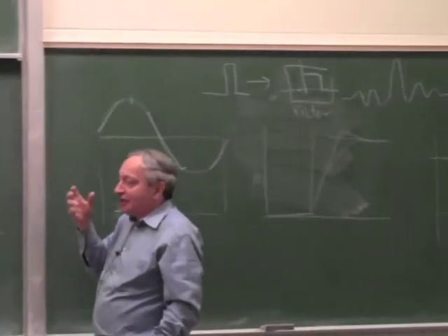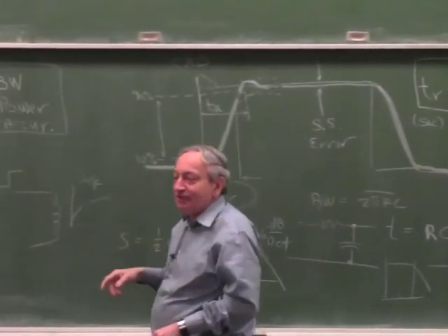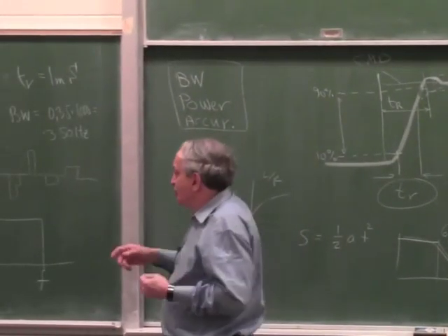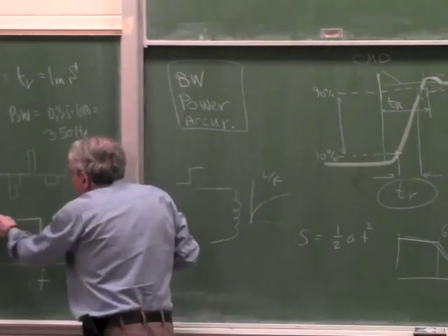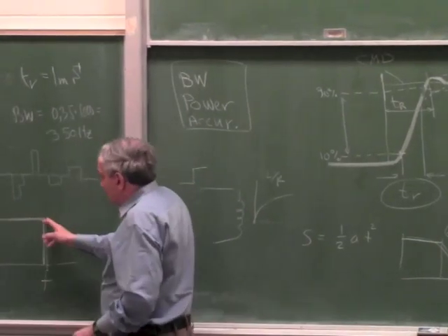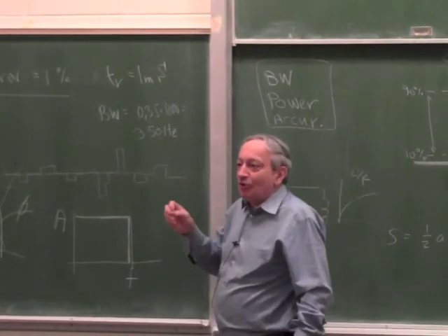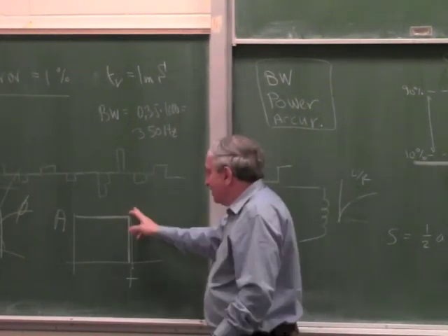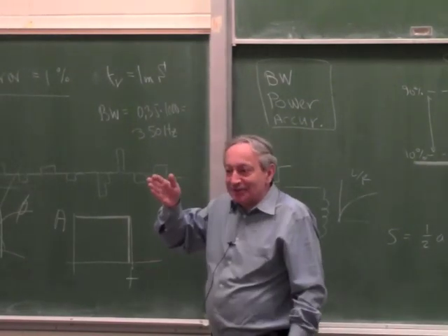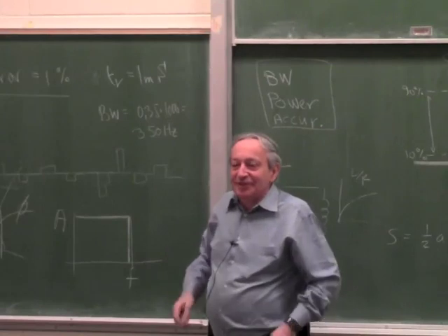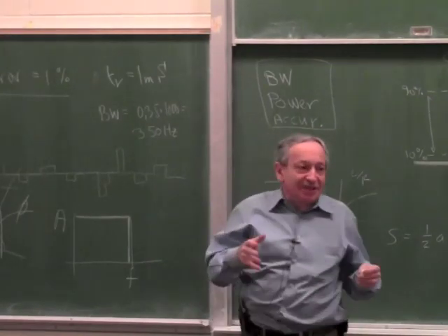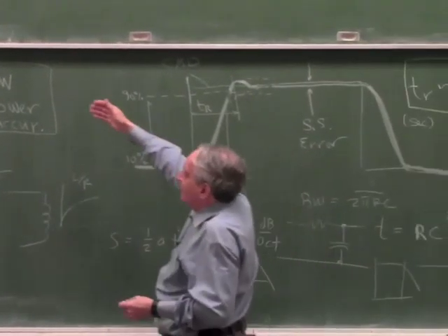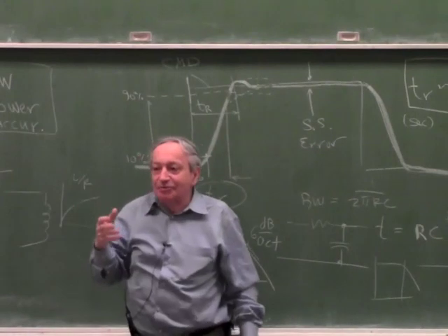So the filters which are very sharp, have perfect forms in the frequency domain, usually have much delay built in and much phase shift built in order to achieve this thing. And the reason you know that is the steeper the slope is, the more poles you have in the filter, because each pole gives you 6 dB per octave. So if you want 100 dB per octave, you need many, many poles, right? And many phase shifts, many delays. So I just want to remind you this chapter because that's critical to design a system. Because the next decision after you decide on this, you have to start thinking about which filters to put in.